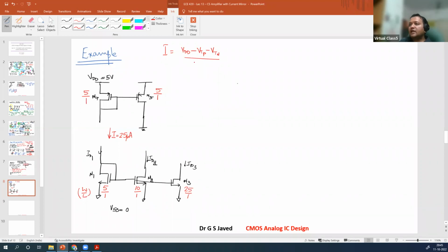Now I will physically add a known resistance called RF to ensure that I get a value. So this will be the RF value that I will add to ensure that I get a 25 microampere current. I might be having other resistor values here, but I will use this RF to get an IREF equal to 25 microampere first.